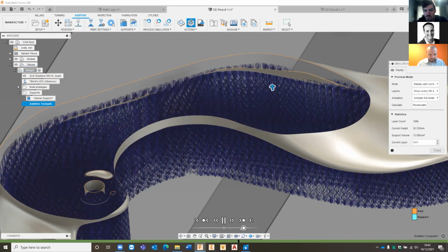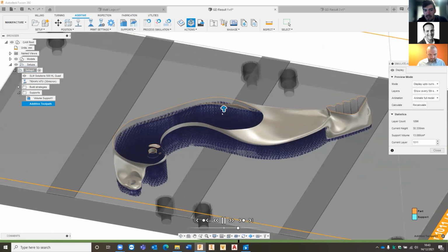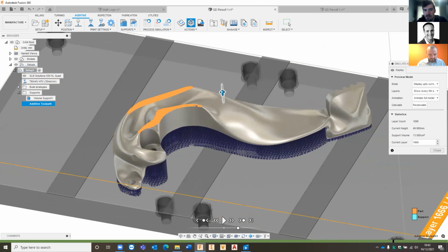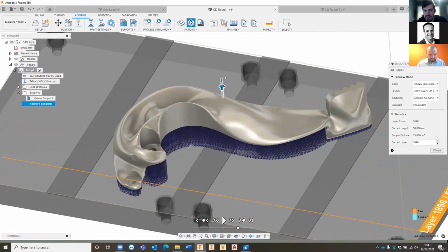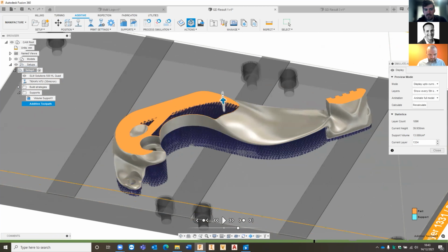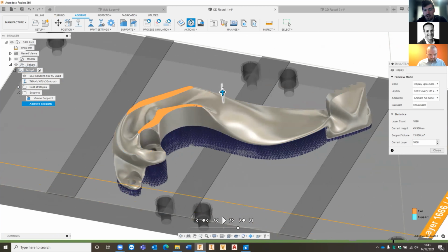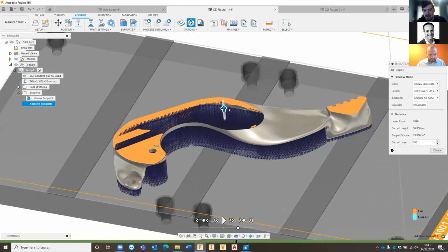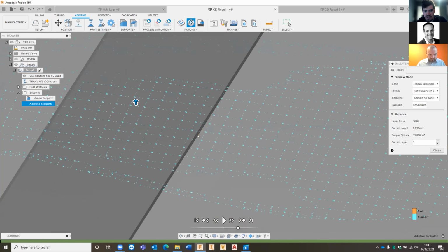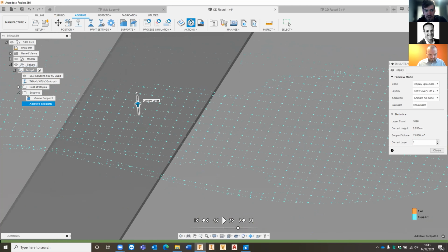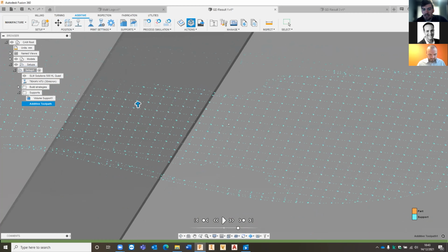So yeah, you've got various ways of viewing this. And again, I can come in and use this arrow and change. If I pause, it'll be better. And I can come in and move this arrow about just to view individual sections and see how it handles different parts of the build itself. As you can see, as it comes closer to the top there, it's got a lot less to then print off. We can come all the way down to the point at which it's printing the supports as well, and view those directly from there.